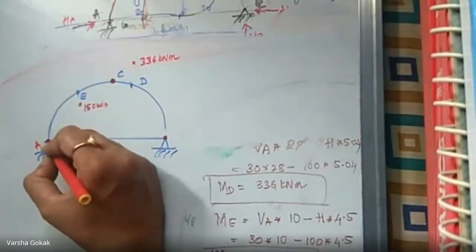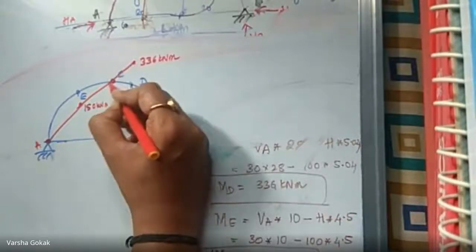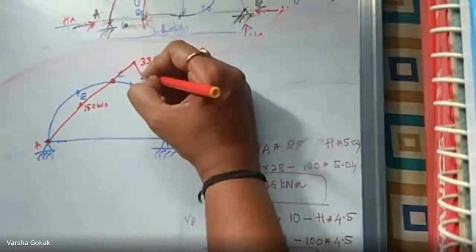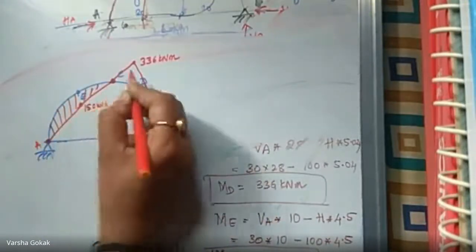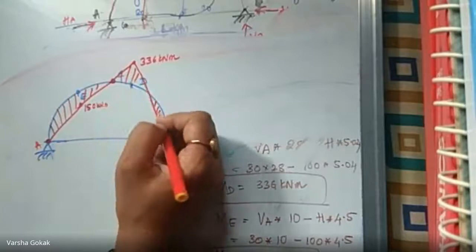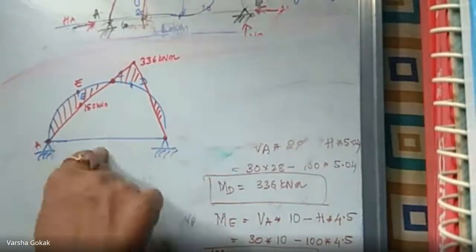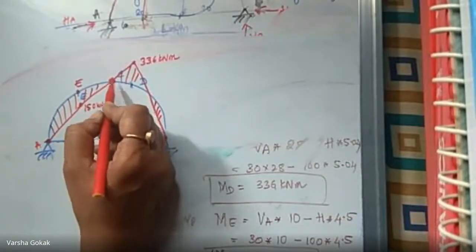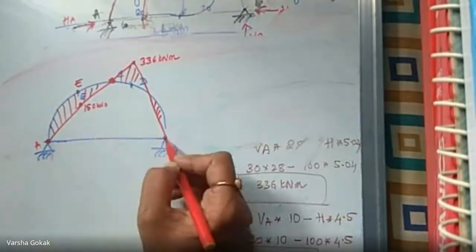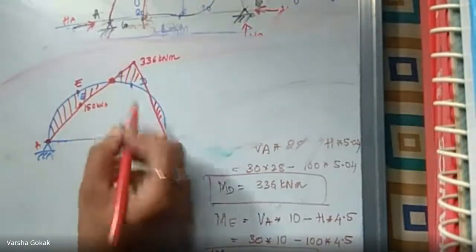How you will do is you will join the dots. Okay. Then it is a point load, no? From there, get down and shade this area. This is your bending moment diagram. This is your E point. This is your bending moment diagram in case of a 3-hinged arch. It is very important you show this 0 because it is a hinge over there. So it is passing through 0. That's why I first marked these zeros. There the line has to pass as it is. E and D, you get 2 values, you just join that line.